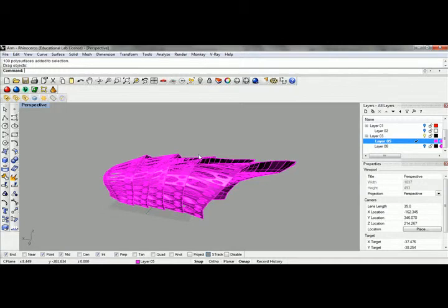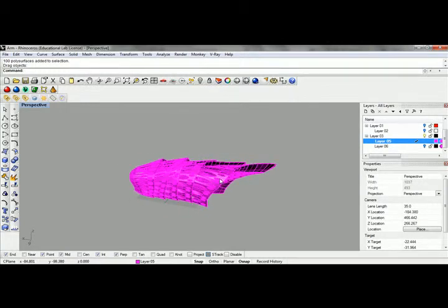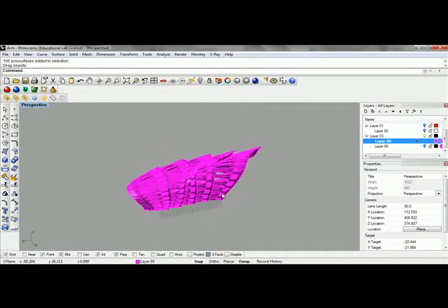Okay, and so whenever you're actually modeling, you need to pay attention to that. Any geometry that you're going to take to 3D printing needs to have that distinct inside and distinct outside so that when you actually slice and dice or extrude, however you're printing, it knows where to place material or where to place adhesive so that it can actually be constructed properly.